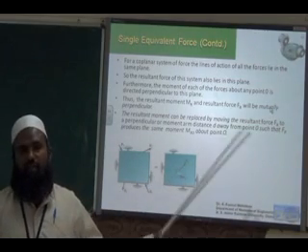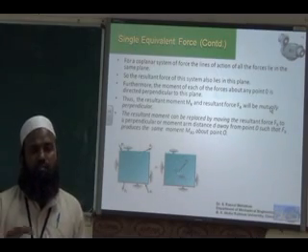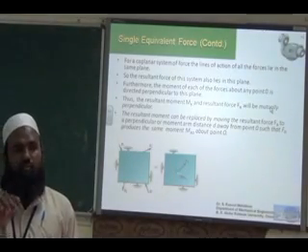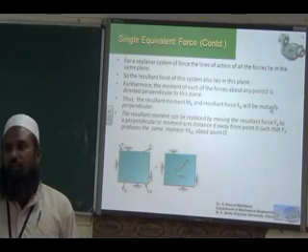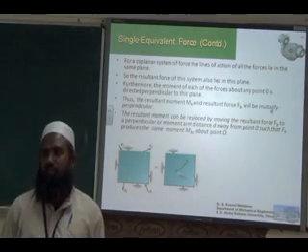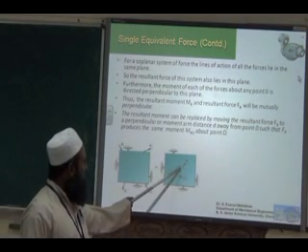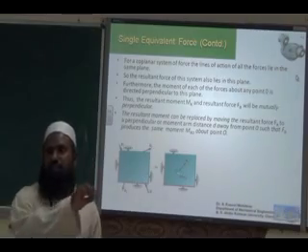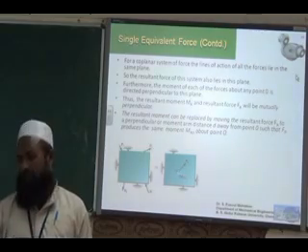We convert all, like the problem example we have seen. First we find the resultant force, then we also find the moment produced by each force about O. Since we are transmitting to point O, we find the moment developed by each force about O. So the resultant moment is also obtained now. Resultant force and resultant moment are shown. Now we convert this resultant force and resultant moment into a single equivalent force.